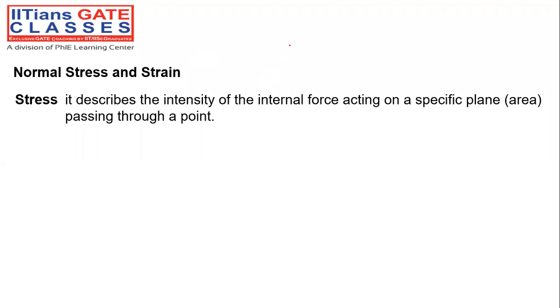Let's suppose we have a bar which is fixed at one end, and we apply a tensile force. At a particular point there is one plane AB, and another plane CD, so we have many planes at a particular point. We need to define one point as well as the plane for defining the stress.